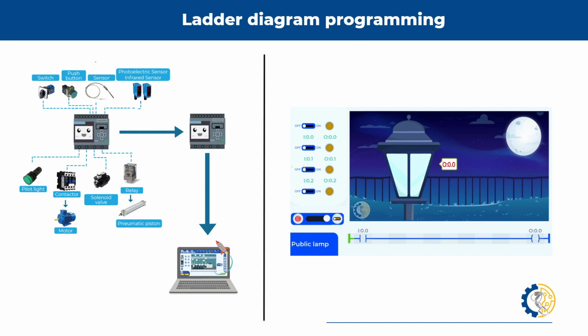So if we had connected this selector to entry point 0, the only thing our PLC is going to do is receive a signal for that input. And all other devices are connected independently with all these inputs. So again, outputs with outputs, inputs with inputs, but they're independent. This can go to output 0, this one to number 1, this selector valve to output number 2, this one to number 3. So why am I indicating this? Why am I reinforcing this? Because all our PLC is going to do is indicate that for my output 0, I have no voltage, or for 0, I do have voltage.